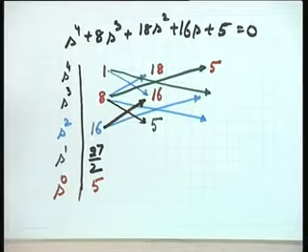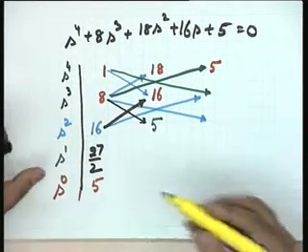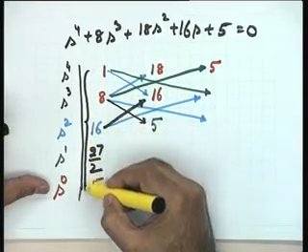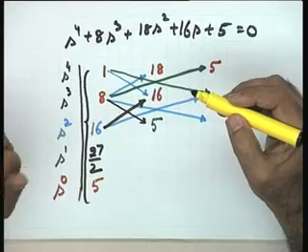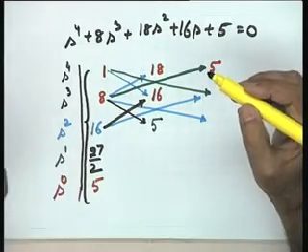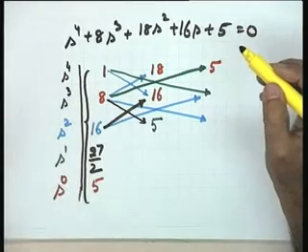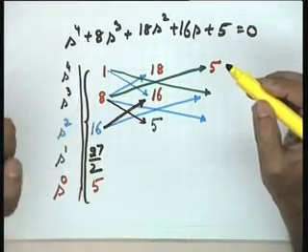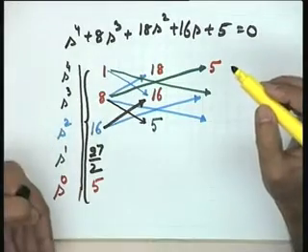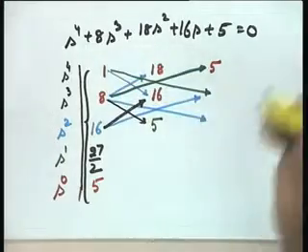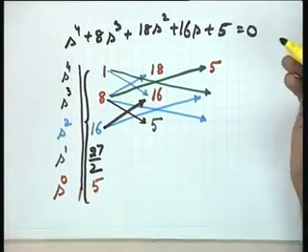Now Routh suggested that in this particular case the answer of stability will be given by examining the coefficients of the first column of the Routh array. And when you examine the coefficients, we have to examine only their signs and not their magnitudes. The criterion says that if there is no change in sign, that is if all of them are positive, because now we can say positive, because the first coefficient has to be positive, we have taken a naught to be greater than 0.